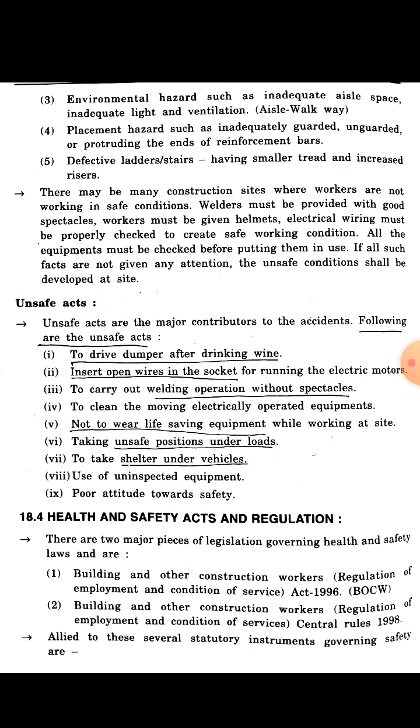Next is placement hazards, such as inadequately graduated or ungraduated protruding ends of the reinforcement bar. Next is defective ladders or stairs having a small tread and increased riser, so it is one type of defective or unsafe condition.